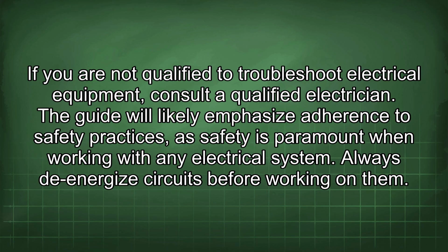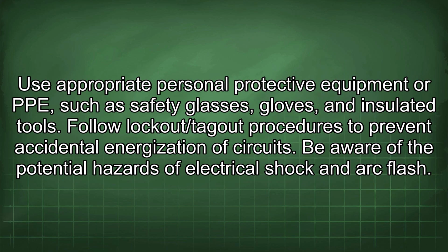The guide will likely emphasize adherence to safety practices, as safety is paramount when working with any electrical system. Always de-energize circuits before working on them. Use appropriate personal protective equipment, or PPE, such as safety glasses, gloves, and insulated tools. Follow lockout/tagout procedures to prevent accidental energization of circuits.